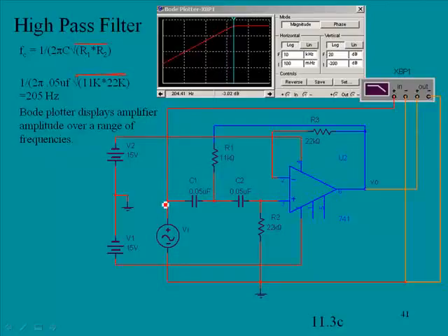One would go to the input, and then the other would go to the output, and then of course the negative and the negative here are both going to ground. But this will allow you to view what this device would produce over a range of frequencies. And like I say, as a user, you could put this up to 1 megahertz if you wanted to, but then it would just kind of go right up here, and then it would be across. By making it more specific here, we're able to really tune into that specific frequency.